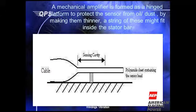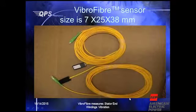Now, in our package design, we made a hermetic seal. There is a packaging cover made with polycarbonate because inside the generator we have to be prepared to have the running temperature up to 150 degrees C. So that forms the guts of our sensor.